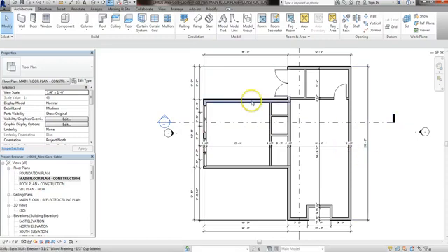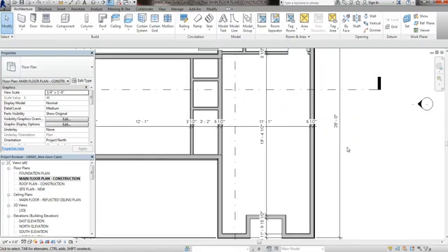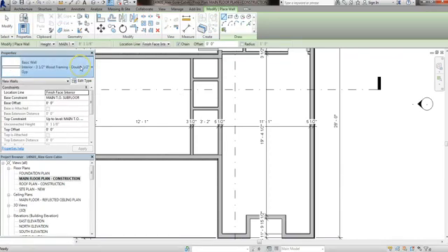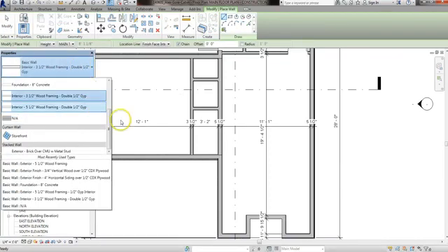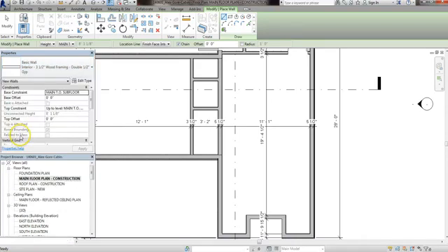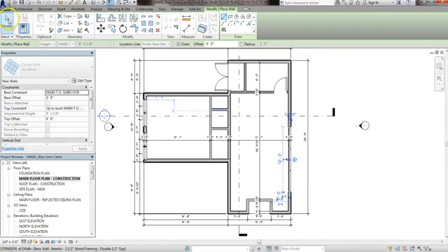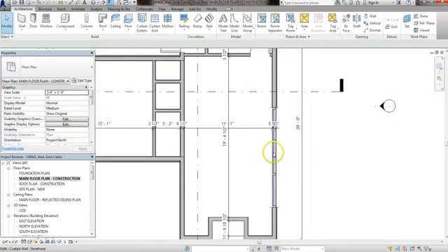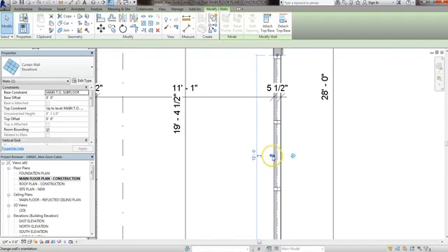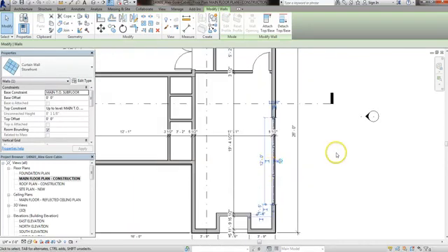The only thing that's tricky and semi-different, normally we don't teach this right away, but people tend to like putting storefront in. And it's pretty easy. It's just another architectural wall, and it's kind of like drawing a wall within a wall. So you go to your wall options, you hit storefront, you start where you'd want it to start, and I know it's 12 feet, and then click to end it. I'm going to rotate this so that your glass is on the outside.